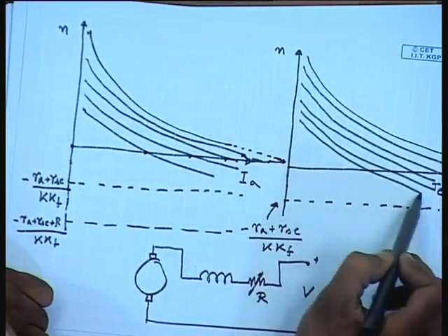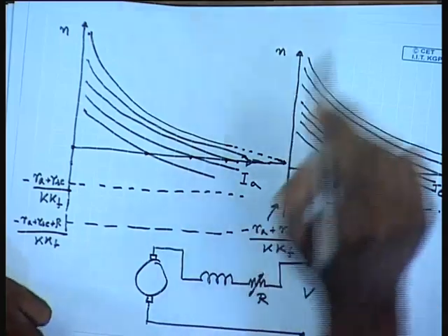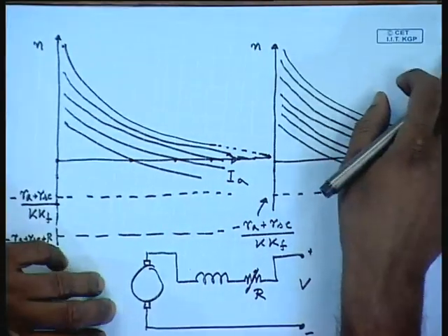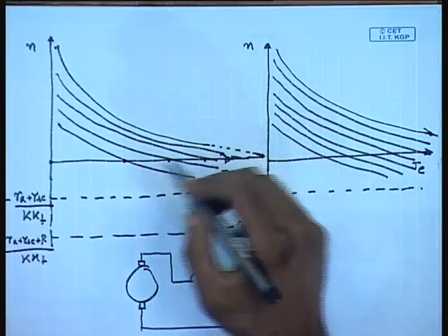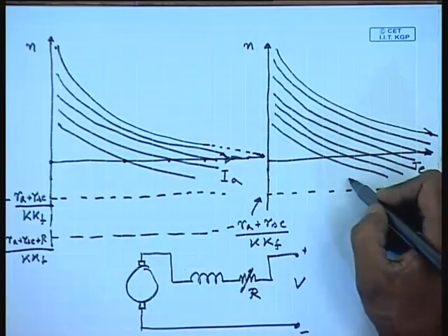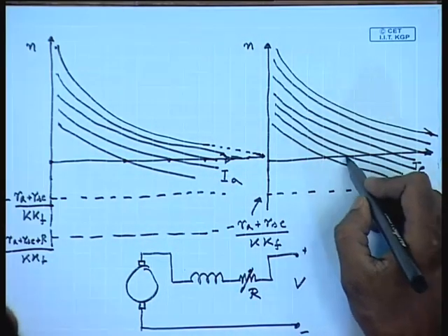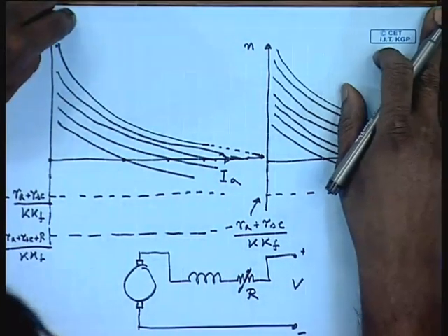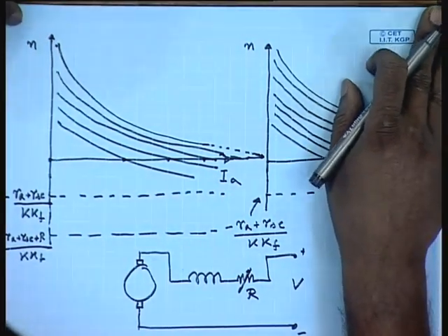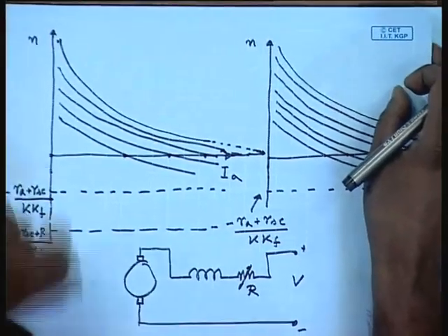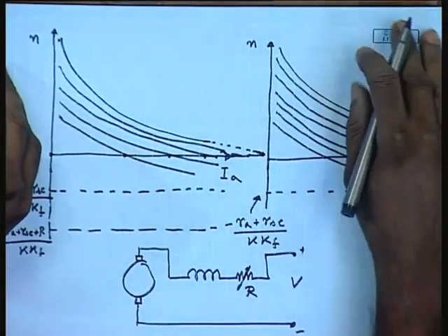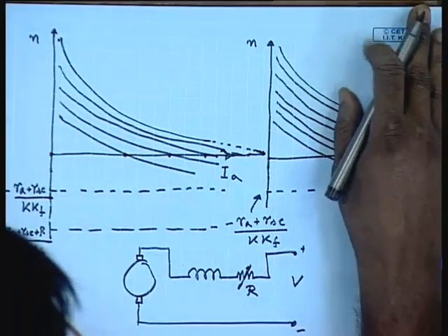However, we see that as the resistance is increased, the current through the machine reduces and so does the torque. Therefore, the machine takes longer time to start. In order to maintain an almost constant starting torque, this resistance should be continuously variable, which is difficult to achieve.